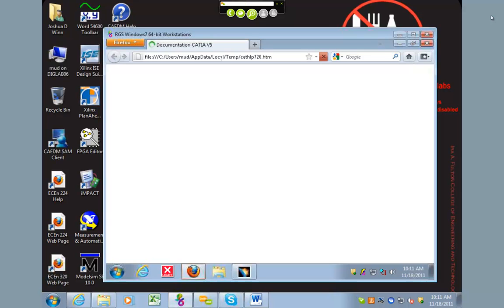All right, so we're going to go ahead and click on Getting Started up here at the top. And then there's Designing a V5 Mechanism. Entering the workbench. And we're going to do a kinematic analysis of a bunch of bars, kind of setting it up to be similar to a chain, I guess you could say, or a 4-bar mechanism. So the part is right, if you scroll to number 3, it says select the rods.cat part. If you click on that, it'll let you open it inside of Catia by default. If you're at NTU and it doesn't give you that option, you can go ahead and save it to your desktop, and then you can open it inside of Catia.